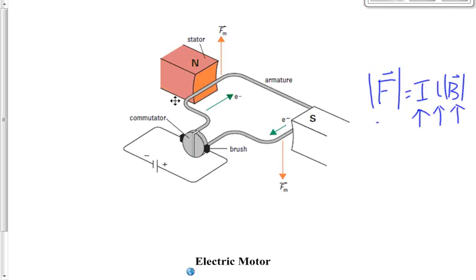He said we want to increase the length of the wire that's exposed to the magnetic field and perpendicular to the magnetic field. Not just increase the length of the wire, but increase the length that's perpendicular to the magnetic field. How do we accomplish that? Usually we'd loop the wire around. So we've got this wire right here that's connected to the commutator, goes around here, around here, around here, and then it keeps going around. We keep looping it around. Every time we loop it around,